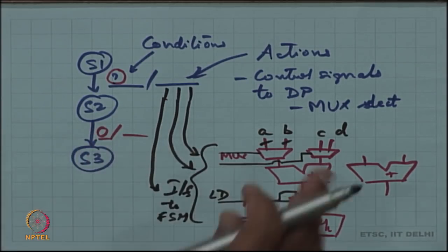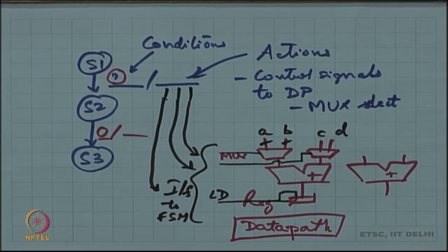Is there a point of providing all those 32 bits to the finite state machine? This is just a 3-state machine, which would be realized using how many flip flops? Just 2 flip flops are needed. So, what is the point of sending all those 32 bits as inputs to the finite state machine? Remember, the FSM is not going to do computation, addition is going to happen in the data path.